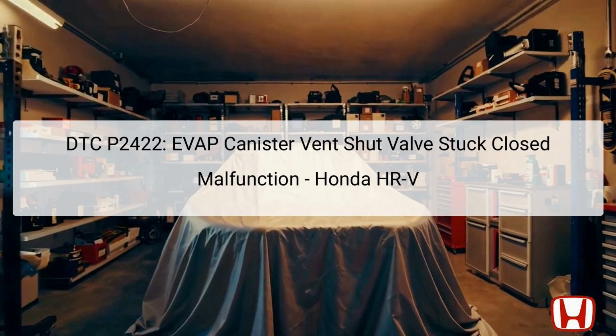In this presentation, we will delve into the details surrounding DTC P2422, which represents a malfunction involving the EVAP canister vent shut valve being stuck closed. This code is critical as it affects the vehicle's evaporative emissions control system, a vital component that ensures any fuel vapors that escape from the fuel system are captured and returned to the engine for combustion.